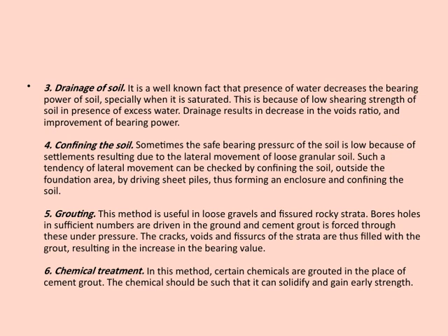Next, confining the soil can be very effective, particularly when the safe bearing pressure is low due to settlements caused by lateral movement of loose granular soil. To prevent this lateral movement, we can confine the soil outside the foundation area by driving sheet piles around it. This creates an enclosure, effectively holding the soil in place and improving stability.